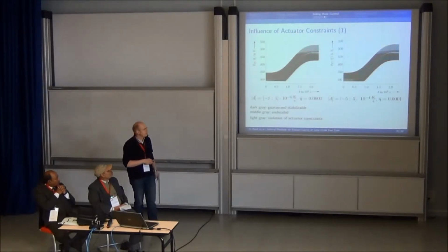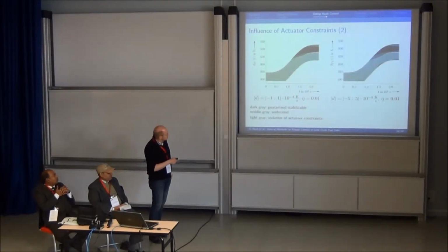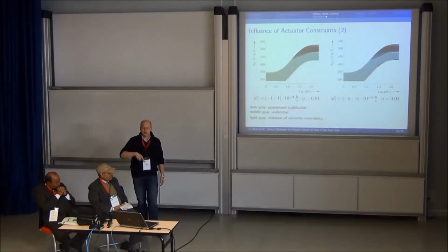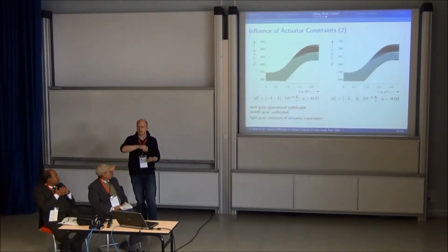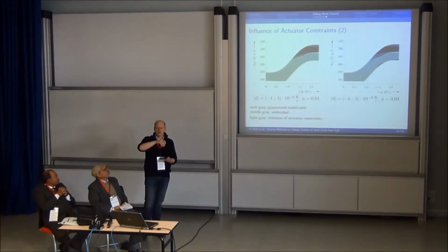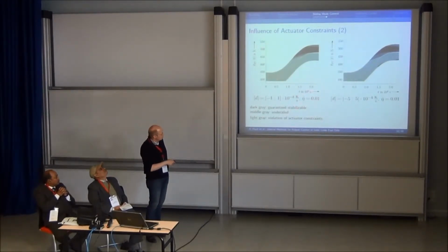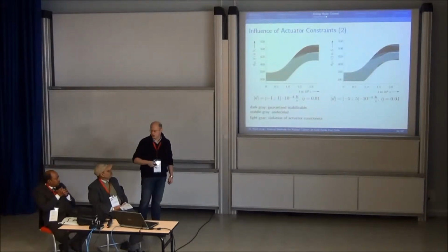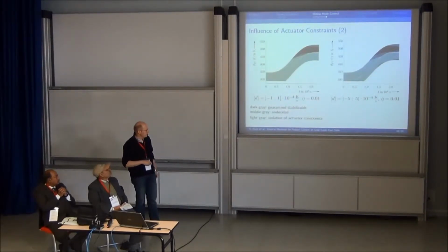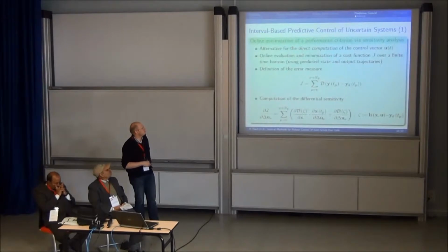system. And here you can see we can shift these regions by just adapting one of these parameters, and this parameter is the parameter eta tilde. This is the parameter that is scaling the variable structure part in the control law, and using a suitable online search scheme for the optimal value, we can define also control strategies here on the top for high temperatures, which prevent overheating here in the interior of the fuel system.